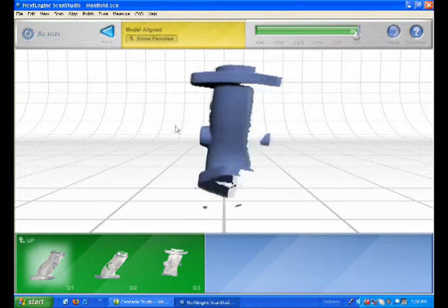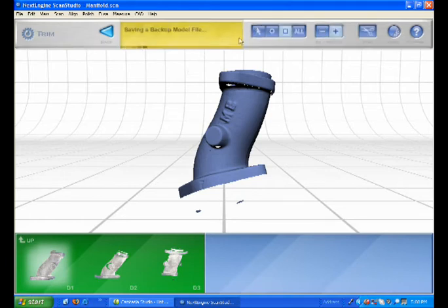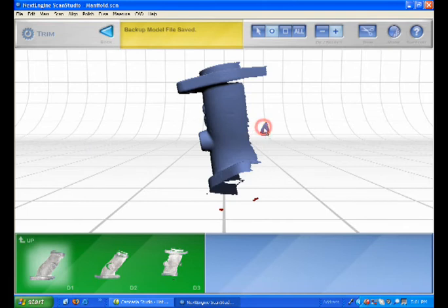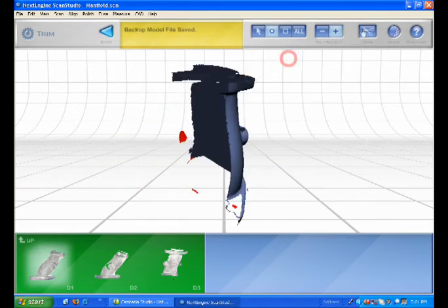So what Ronnie's going to do here is clean up those few extraneous points, and then he's going to go ahead and fuse the scans. Again, if you remember from our polish menu, it's very easy to go down and clean those scans up. You can do your cleanup once it's completely aligned and all the scans are together. There's a lot more data there, so it's more processing time to deal with, but it's probably better to scan at the individual thumbnail level, because it's going to be a lot faster and easier for you to trim. So Ronnie's finishing up his trimming here.